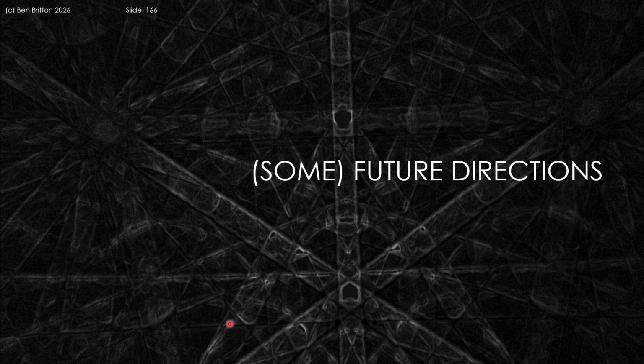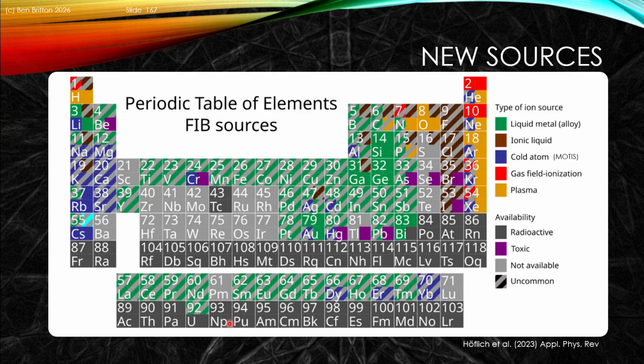So let's look at some future directions. Telling the future is incredibly difficult, but we can look in the literature about where people are excited and opportunities and where they sit. So one of the areas of activity is to look at new source types. We've actually seen a few of these sources, or older sources, although they've been limited in the material systems that we're looking at. So we can have effectively things like the gallium source, which is a liquid metal or alloy-based source, and so if you have the appropriate material that has a low enough melting temperature, you can then use that to wet the surface of the tungsten filament and then enable that to have a liquid metal source. And that opens up a range of different systems.